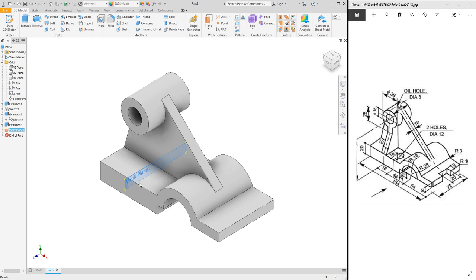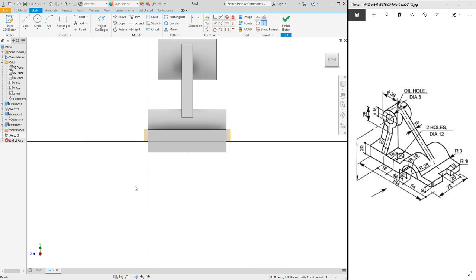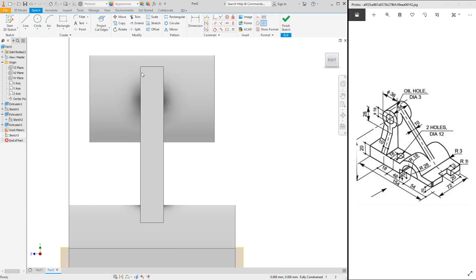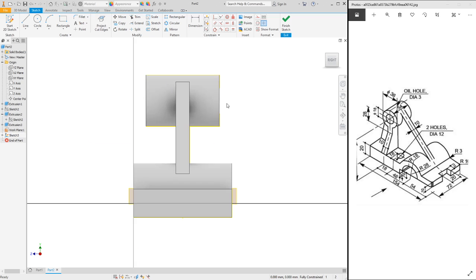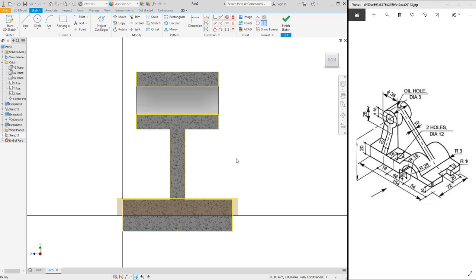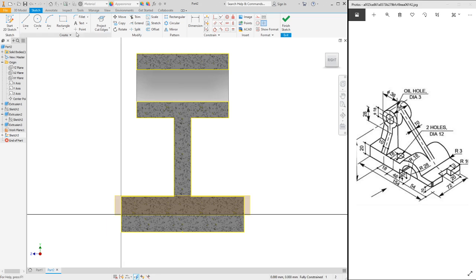So click on it. Click on create sketch. All right. Then here we can again project the cut edges. Then after that, we can slice the geometry so that we can see clearly where we are working. So we click on that and then right click on the workspace and click on slice graphics, sorry.